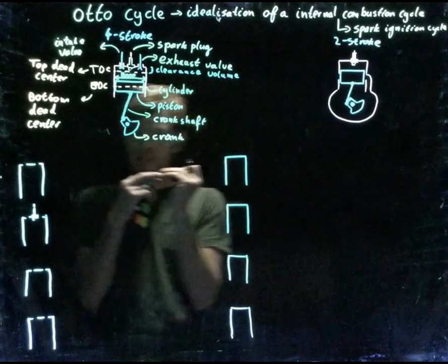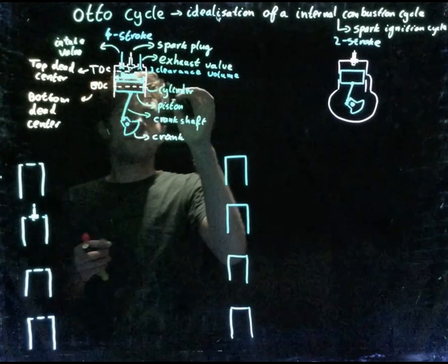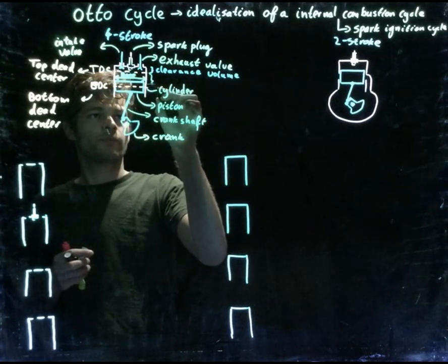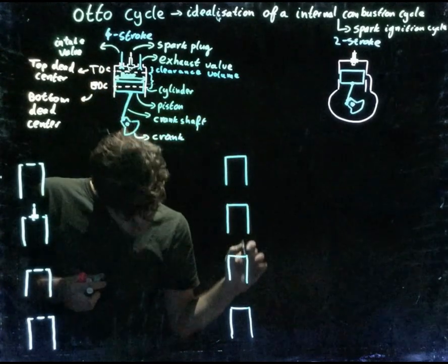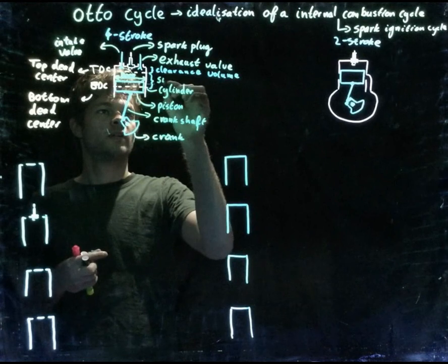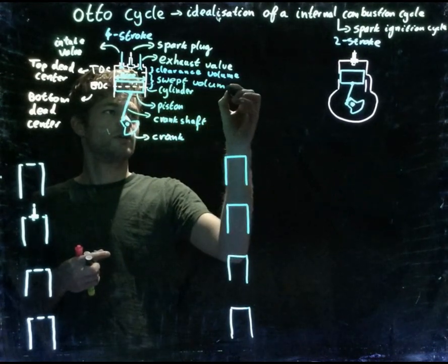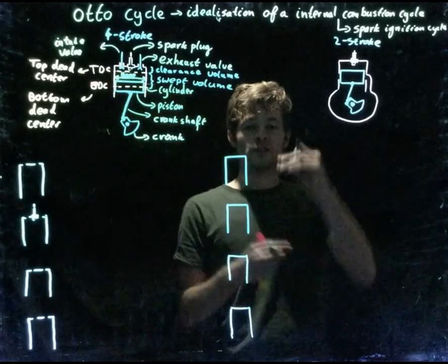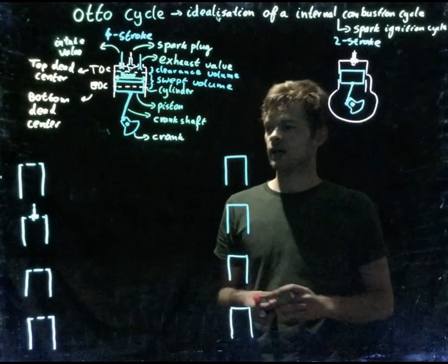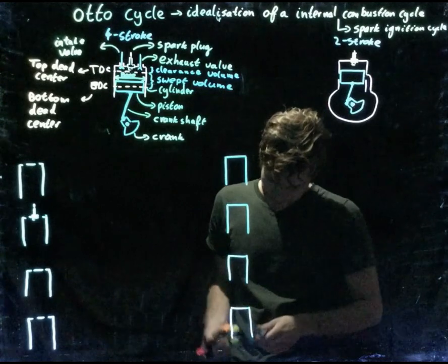That's the clearance between the piston and, for instance, the spark plug. And then we have this volume, which has a name as well: the swept volume. The swept volume is the volume that's refreshed in each stroke. I'll explain in a minute what I mean by refreshing.